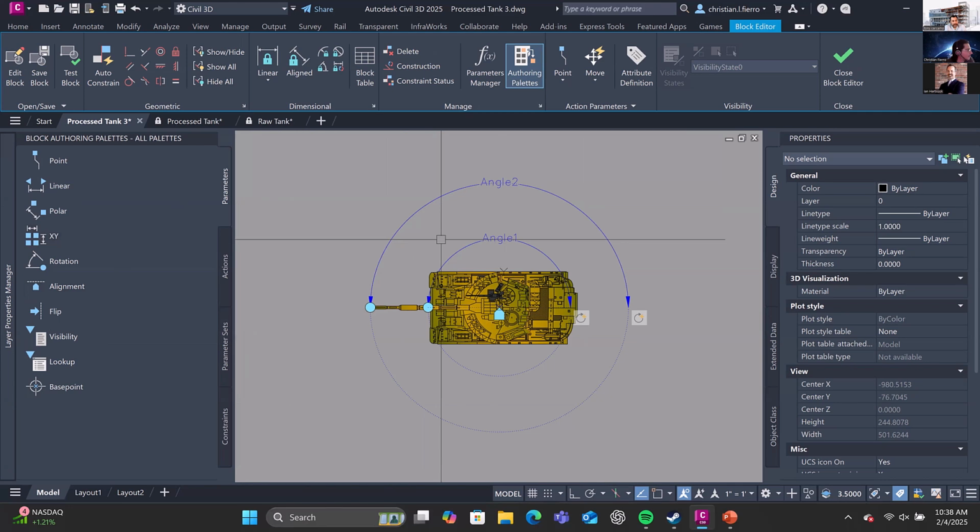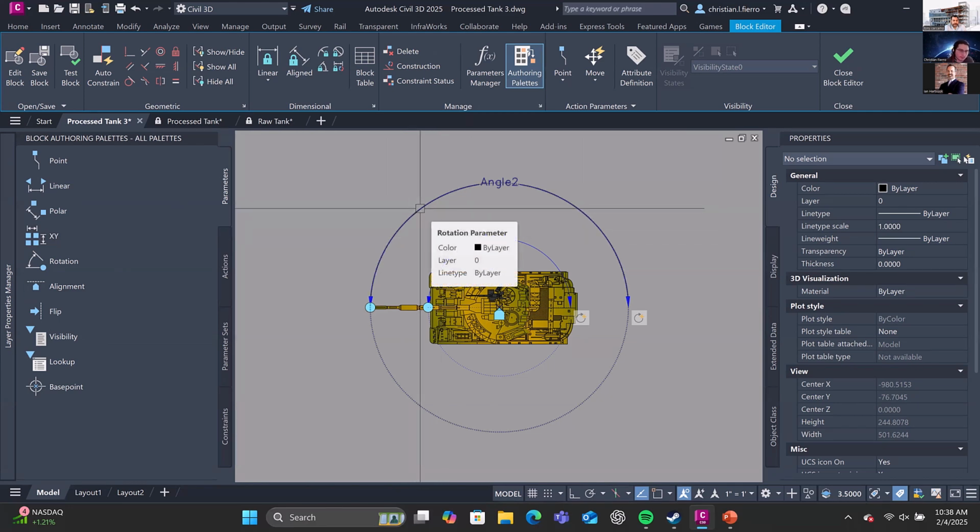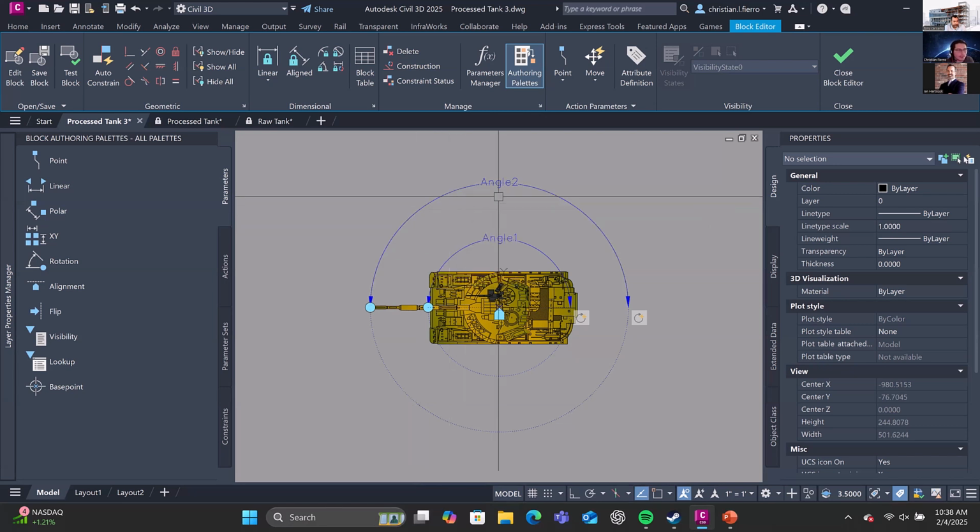The issue with visibility states is you can't have more than one active. That's the issue I was coming across: I was trying to have too much going on in different visibility states and overly complicating it. Whenever I simplified it, I was able to have just three visibility states compared to seven, and they all work more cohesively together.